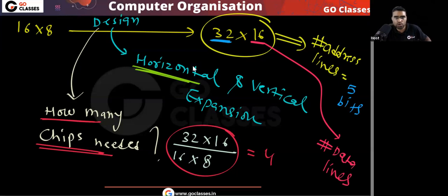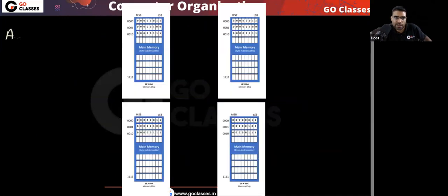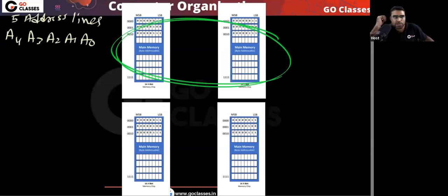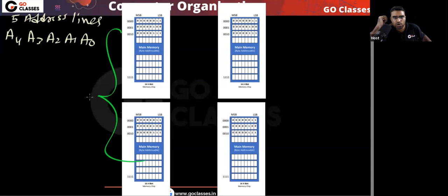Now tell me, do you need a decoder? Remember, you need 5 address lines: A4, A3, A2, A1, A0. Total 5 address lines you need. Do you need a decoder? What is the size of decoder you need? You tell me. For this horizontal arrangement, do you need a decoder? No. You only need a decoder for vertical arrangement. Vertically, you tell me.